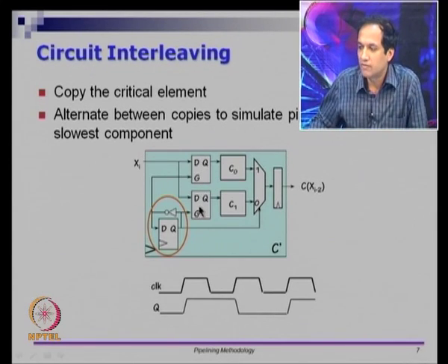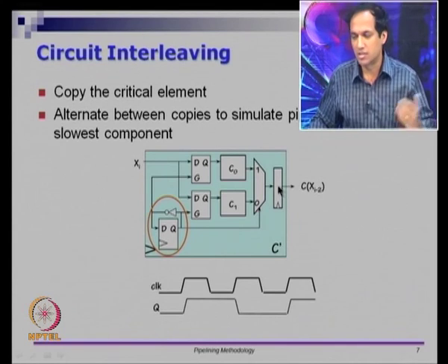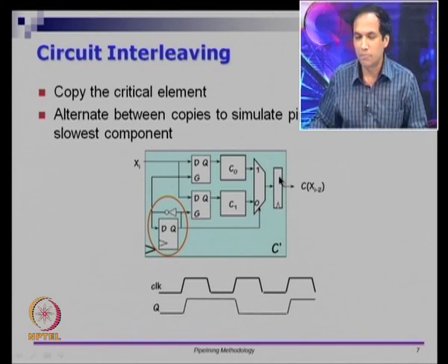So, we have some kind of a latch here. This is a D flip flop, and so this is a gated D latch and this is a gated D latch, and this is a flip flop. So, the output of this always has a flip flop. Because it is a pipeline circuit, a K stage pipeline should always have a flip flop. So, I put a pipeline register here, and since the output could be coming from either this logic or this logic, I need a multiplexer.